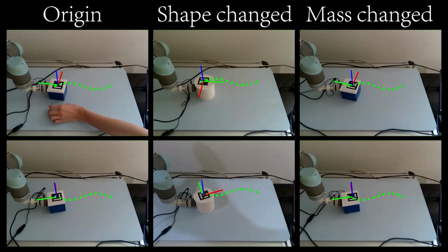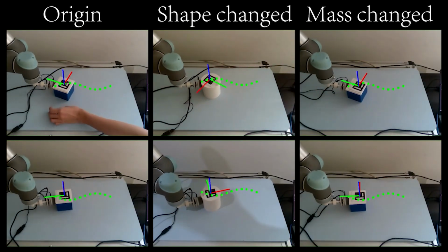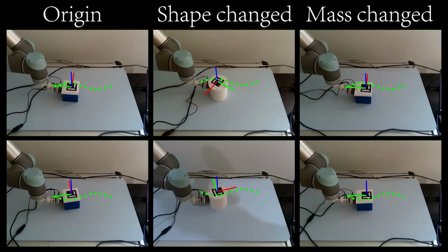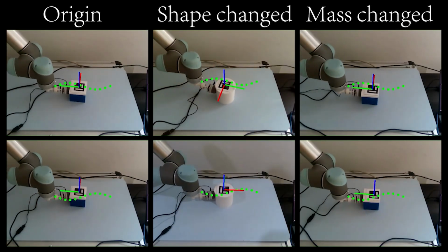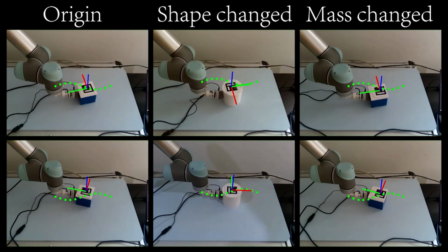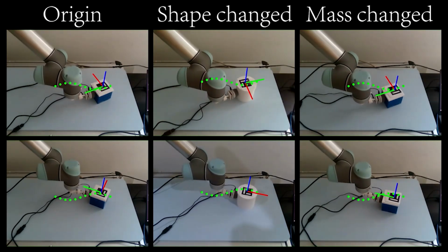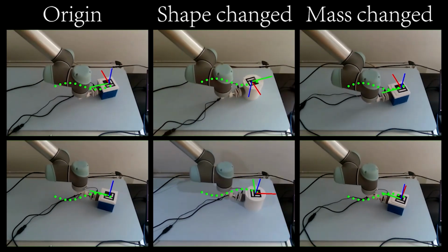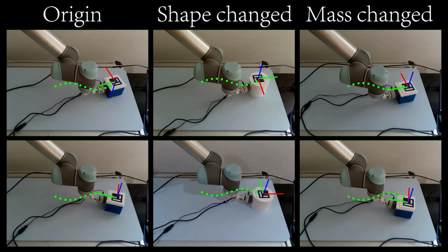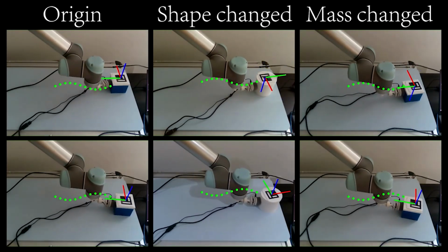We first conducted experiments using the reflection-based tactile sensor. In the push task, we examined the performance of our policies under various physical parameter settings, including initial orientation offset, mass offset, and object shapes. The results demonstrated that the policies trained using our approach exhibited notable robustness.